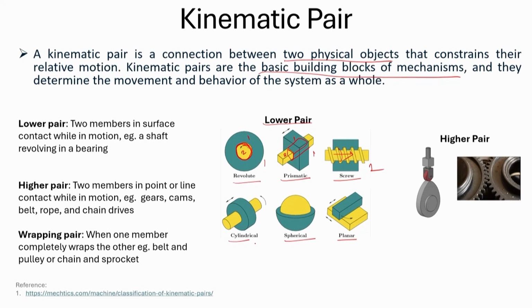Cylindricals are going to give you 2 degrees of freedom, planars 3 degrees of freedom. Spherical also you are going to get, depending on the situation, 2 to 3 degrees of freedom. That is, you can have 3 rotations, all of them together, and in some cases 1 rotation may be constant. So, these are all the definitions of lower pairs. Then you have higher pairs.